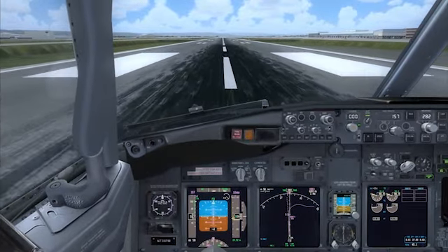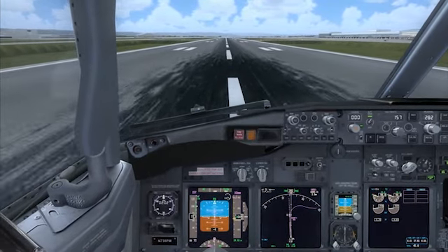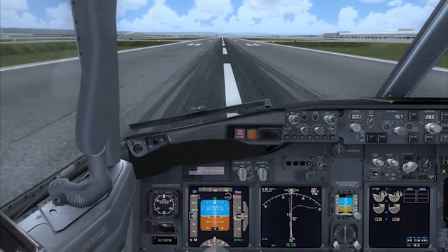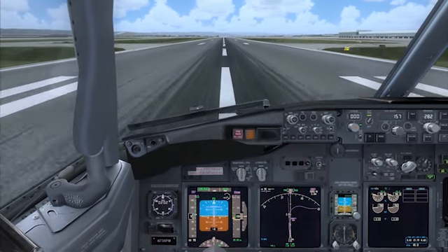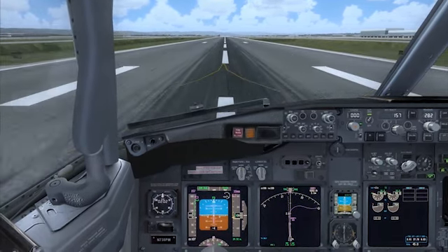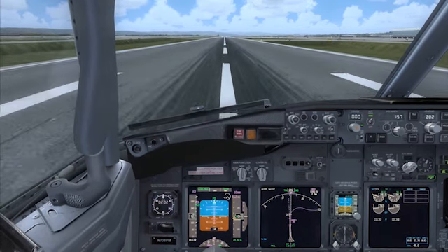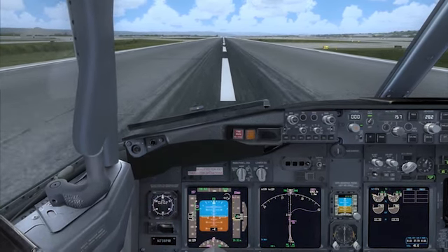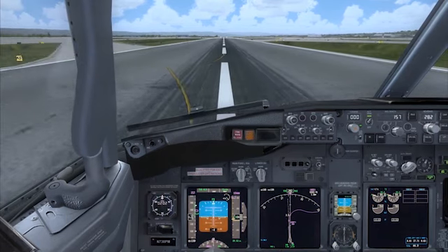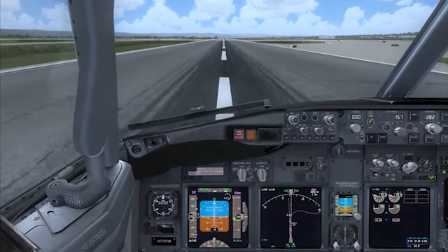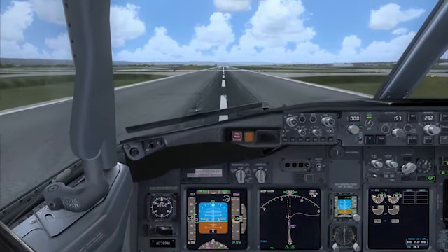FCC data used for commands to the flight director and the autopilot system are actually filtered differently. The commands you see on screen when flying with the flight director is not the same data the autopilot uses. The autopilot data is more filtered, detailed, and looks ahead to a greater degree.